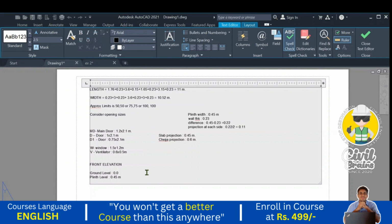The plinth height depends upon the road level and the water table. Depending upon the water table and the road height, we consider the plinth level. In most cases, from the road level, we consider 0.45 meter height of the plinth. Sometimes it goes higher, sometimes less. Don't go less than 0.45 meter, because in the rainy season there is a chance of dampness of the floor. So most of the time we consider 0.45 meter as the minimum plinth height.